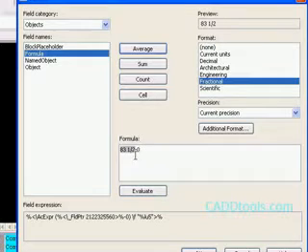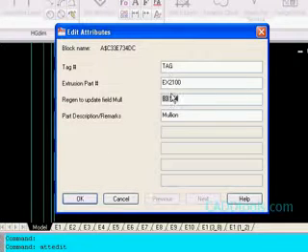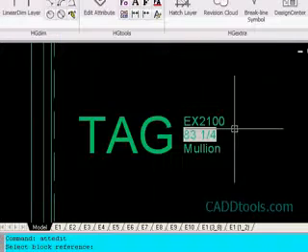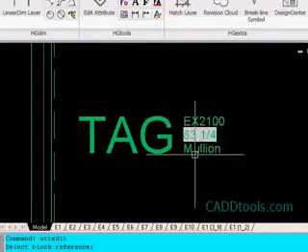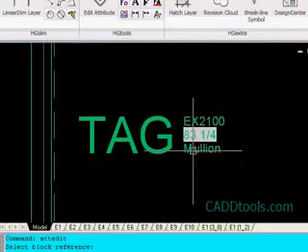Right now all of them are associated to a formula, and it is minus 0 inches, could be plus 0 inches, but that way it stays in formula mode, and then you can do minus 1/4 of an inch. Then it would automatically take that dimension and subtract 1/4 of an inch. In storefront, we don't really have that situation too often.